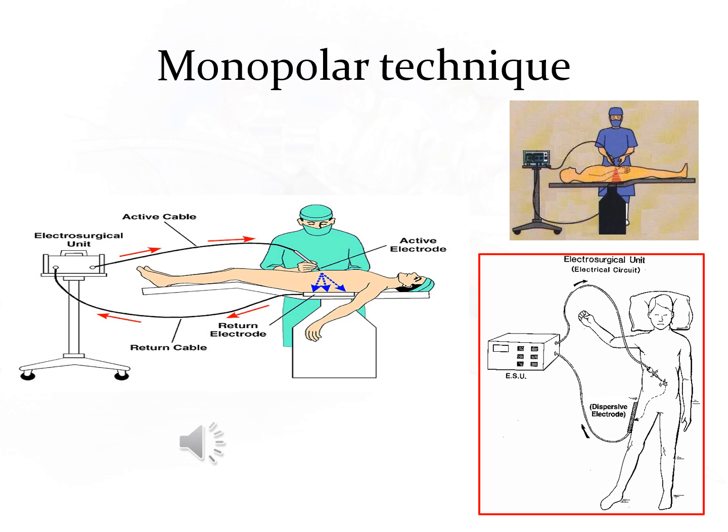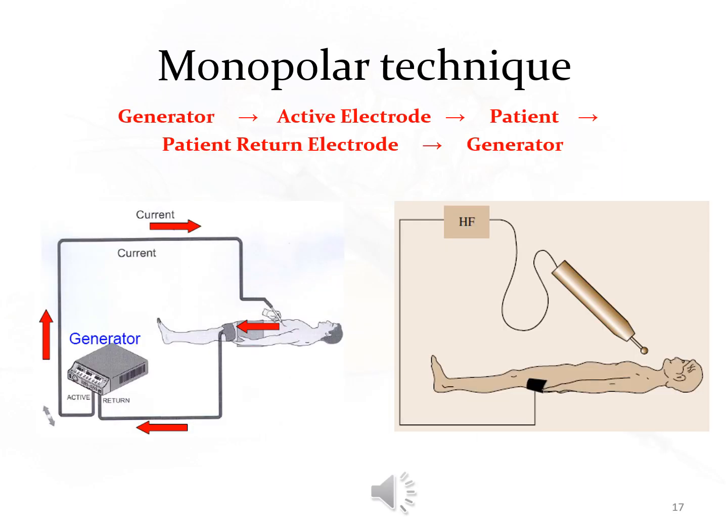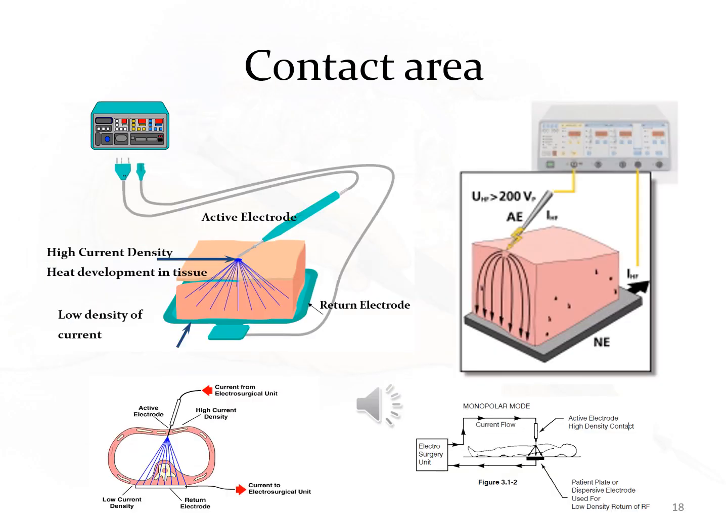And 5. Radiofrequency oscillator, 300 kilohertz to 3 megahertz. Active electrode: used for achieving the desired surgical effect, or small contact area. Dispersive electrode, return electrode: at which no electrosurgical effect is intended, or large contact area. The contact areas of the two electrodes differ greatly from one another.